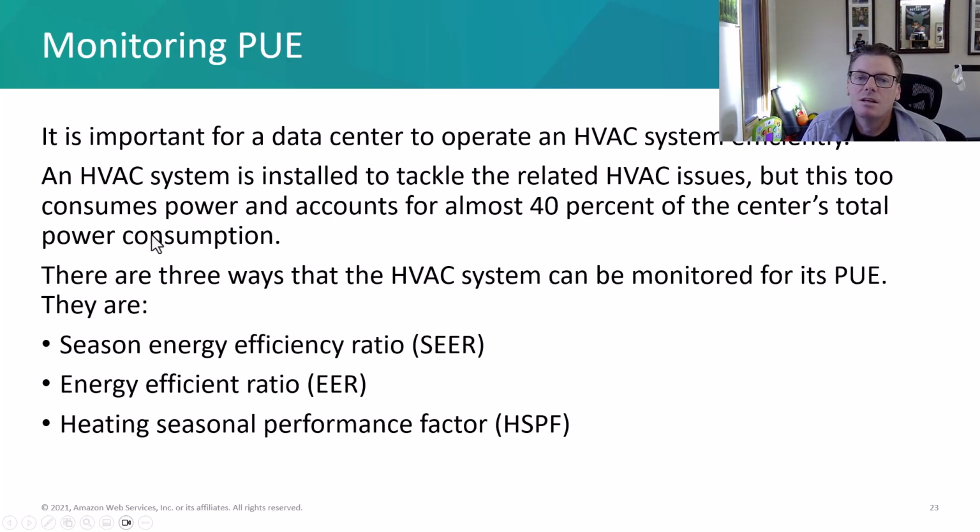All right, it's also important that we run that HVAC system efficiently, and it tells us here that the HVAC system is going to account for almost 40% of the data center's total power consumption. So just to keep the temperature, humidity, and airflow maintained is 40% of the data center's total power consumption. So that's almost on par with what your IT equipment is going to use as well.